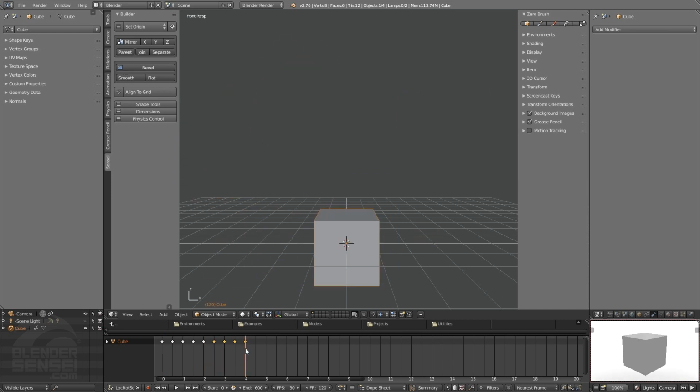And if I hold my right mouse button to drag the timeline cursor to the last frame, down here where it says FR for frame, we'll see that the total length of this animation is only 120 frames, whereas our animation itself is set up to be 600 frames. That's why the cursor keeps going, and you can see the frame display here, even though the animation frames have stopped. So you definitely wouldn't want to render all that out.